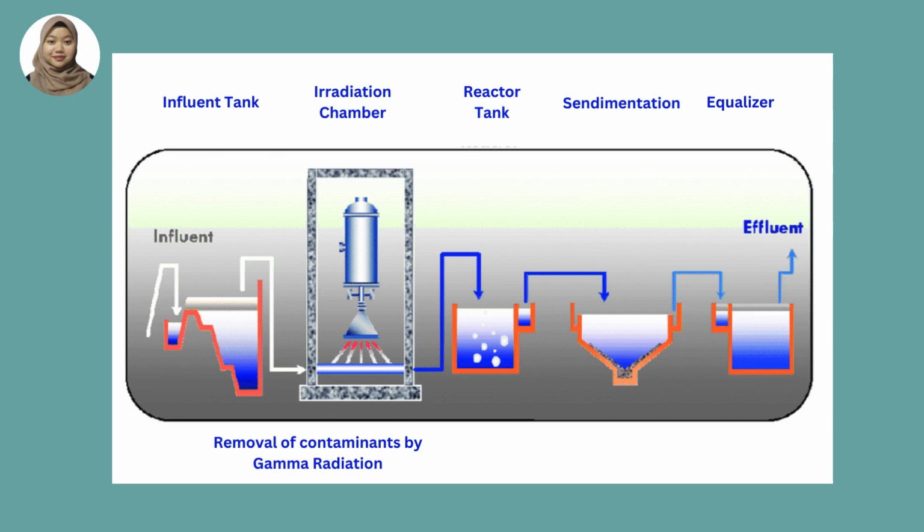The process of wastewater treatment. First, the wastewater enters the system and is collected in the effluent tank. This tank is crucial as it stores incoming wastewater and helps in equalizing the flow and load before moving on to the next stage. During the pre-treatment, larger particles and debris might settle out or be removed. This step is essential to prevent clogging and damage to the downstream equipment, ensuring smooth operation of the treatment process.